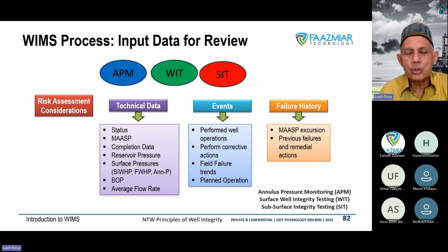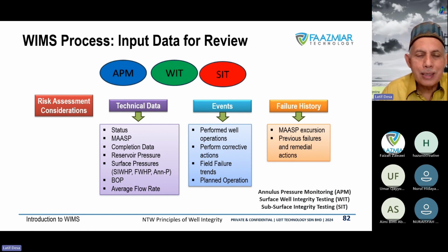So if the well has good health, production can continue. If there's any issue, they have to shut down the well, stop production, and do the repair job. So repair jobs normally come up in a group. You have sometimes not to spend, because when you come to the platform, you normally be involved with some heavy lift, you have to shut down the well. So the word shut in the well is not a favorite subject. That's why you have to come in a group so that once you go in, do the rigging up with heavy lift, you have to shut down the well and it can work on 3 to 4 wells to be more effective to handle the production shutdown.